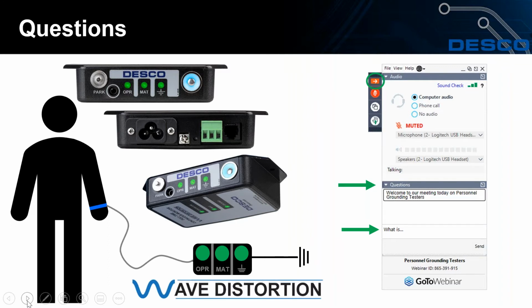And so we also incorporate that into our single wire monitors. Our monitor will also alarm and let you know if you have a personal safety issue, if that resistor has shorted. So that's something you should definitely keep in mind, or a feature you should want when you're choosing continuous monitors.